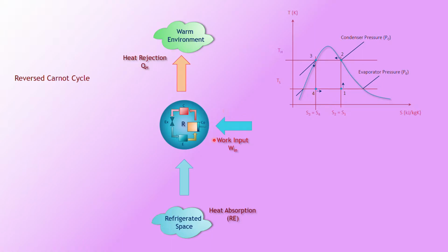For heat engines it is a turbine, where you have work output. For the heat engine cycle, usually the arrow is pointing downwards. This is pointing upwards. So with the help of the compressor, circulating the refrigerant or bringing the pressure up to a certain amount of pressure with relatively high temperatures. So here is your compressor. This is the condenser. Usually the condenser is condensing tubes and the evaporator is evaporating tubes.